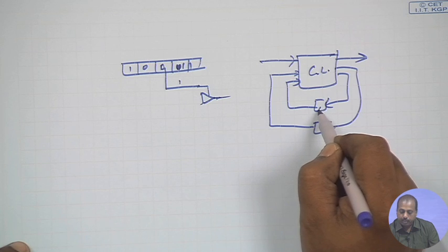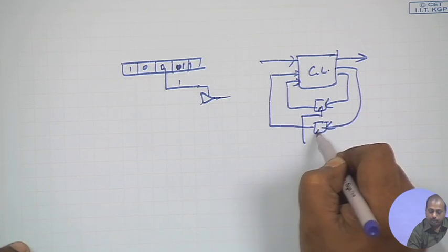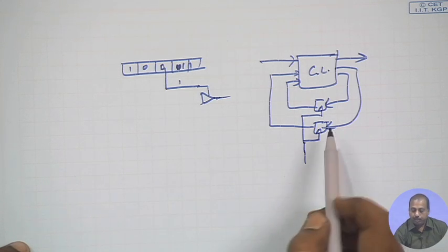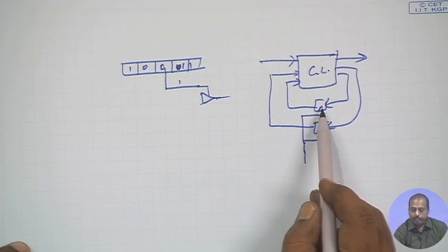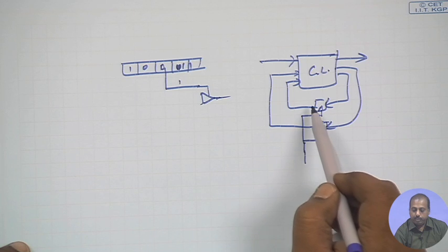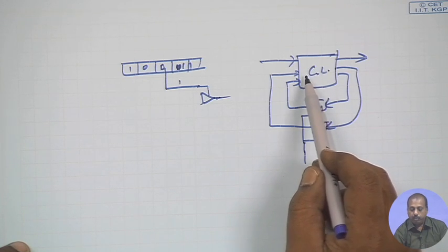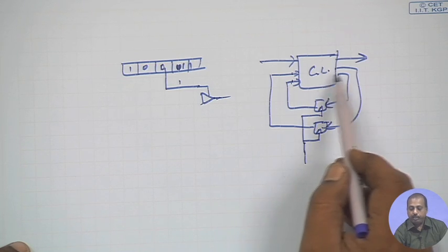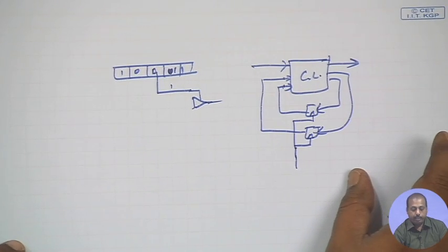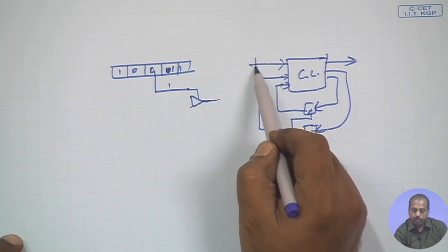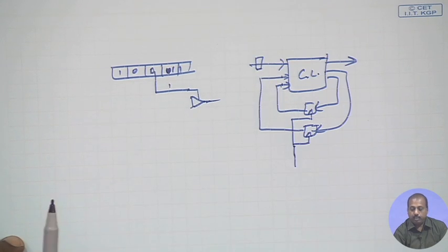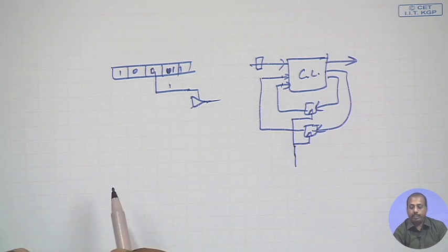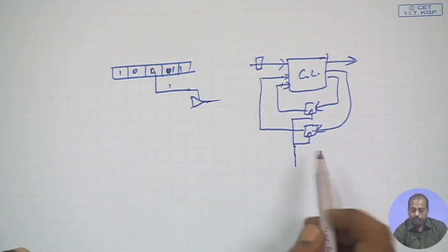what we can do is disable the clock signal that we have, so that these flip flops will not change their values. If they do not change the value, this combinational logic will also not get any change in its pseudo primary input, and possibly it will not change the pseudo primary output as well. You can also have some sort of latch here to ensure that the primary inputs are also not changing, so that this combinational logic becomes totally idle. Now, this is known as clock gating.